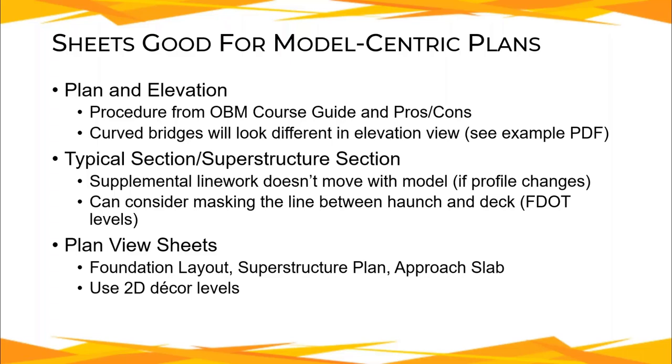That's kind of Bentley's term for the 2D line work that gets automatically generated by OBM, based on the 3D model elements. So you just turn off all of the 3D stuff and you're kind of back to working in your normal 2D world, and you can use that place name boundary tool and really crank out any of these plan view sheets relatively fast.